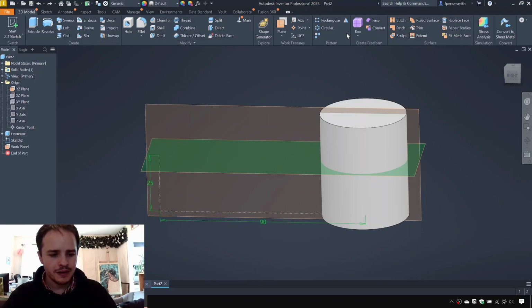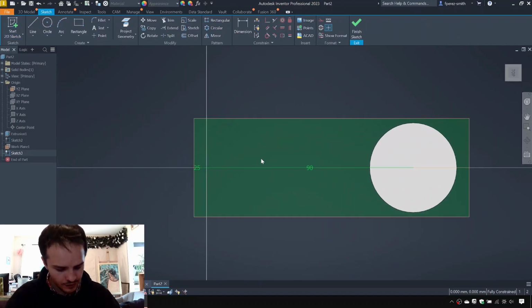Okay, so what we're going to do is make the cross section of that barrel shape. So we'll come along and make a sketch on this plane. And we have to take some measurements. So we can see that the barrel shape, we're going to use the radii. We can see that the major radius is about 20. And then about 18 or so represents it.